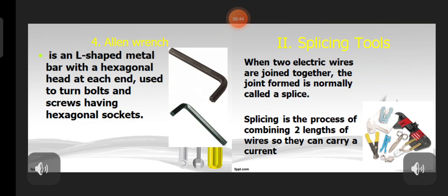When you need to use the Allen wrench, stick the short end of the L shape into the bolt head and press down on the longer side of the L to turn the bolt. Of course, the Allen wrench will only fit in a hex bolt, a bolt with 6 sides. So don't try using the Allen wrench to screw in any other type of fastener.